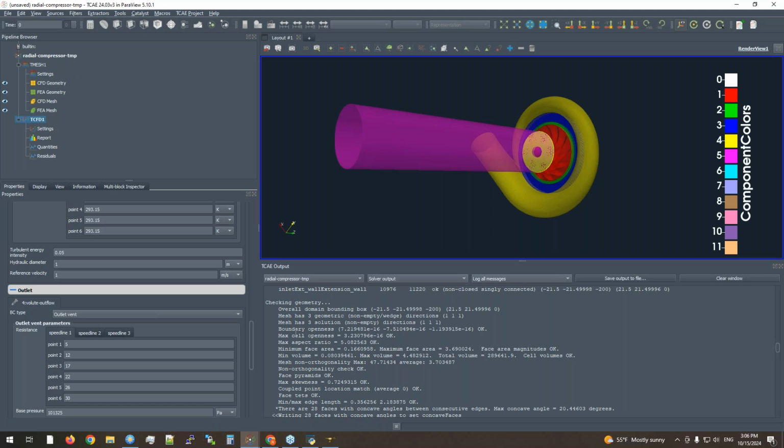Let me add that all these points are run within a single simulation. So every next point is initialized by the previous point, which speeds up the convergence. It looks like, let's say, 18 different simulations, but inside it is run as a single simulation, jumping from one point's result to initialize the next point. That speeds up the whole process, and the result is a one-click simulation. So I just would like to add this information.